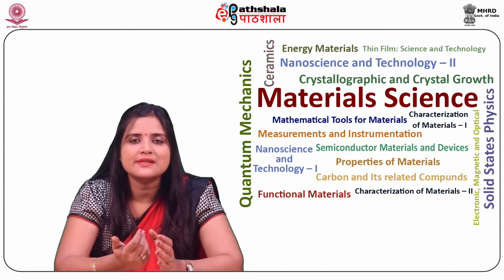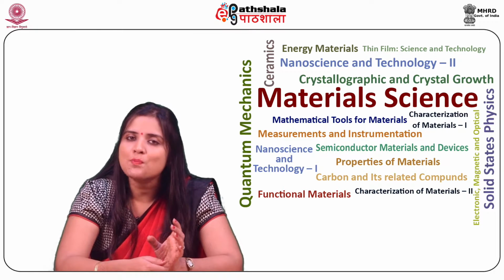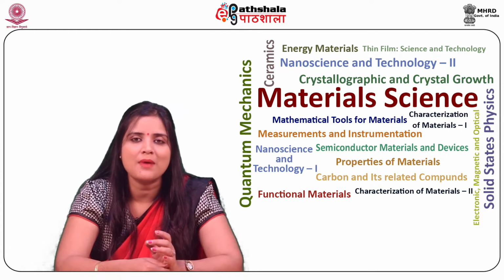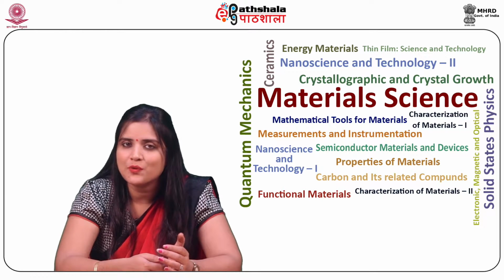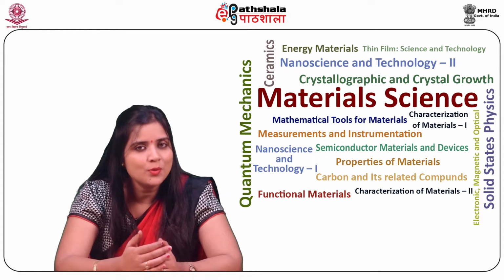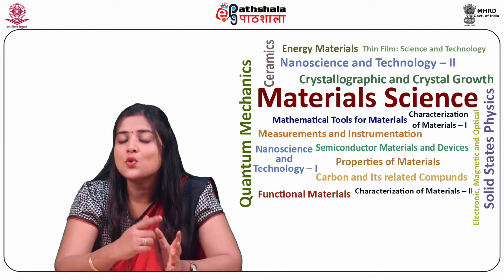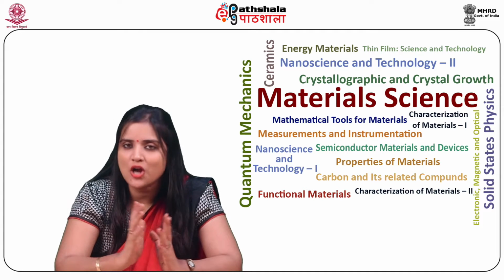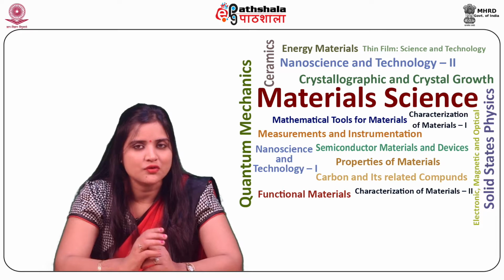Let us now discuss about the closed loop op-amp configurations. An op-amp that uses a feedback is called feedback amplifier or closed loop amplifier. The name closed loop is derived from the fact that the feedback forms a closed loop between input and output. The feedback may be positive or negative.